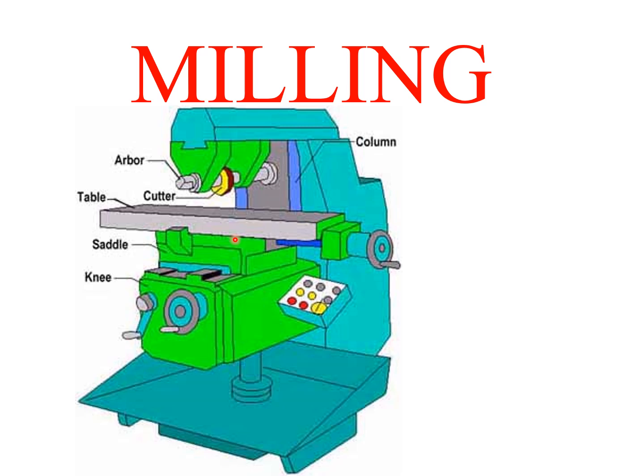Then cutting depth and cutting width are restricted by spindle power, the transmission power of the machine tool, material type, tool parameters, coolant, machining procedure, and stiffness of the machine tool workpiece system. And they have a great effect on tool life.